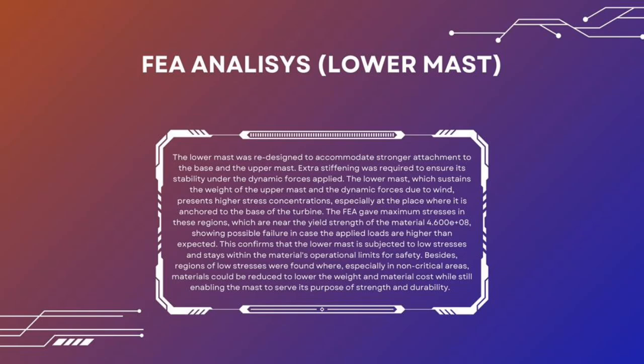The FEA gave maximum stresses in these regions, which are near the yield strength of the material, 4.600E+08, showing possible failure in case the applied loads are higher than expected.